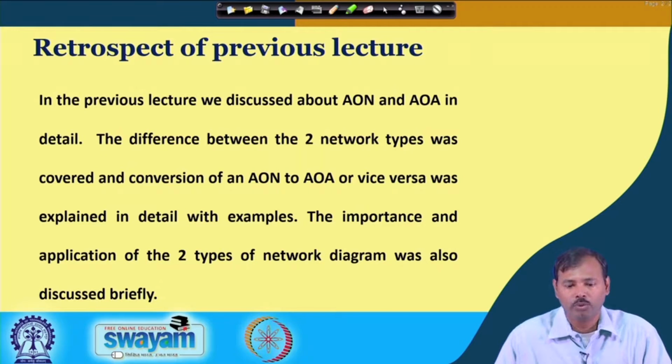But to cater to that problem, the activity on node diagram is much easier, where the jobs are identified in the nodes and thus the predecessors and successors can be easily connected with arrows from one node to another. In the activity on arrow diagram, the nodes only show the initiating and terminating points, and that is why arrows are depicting the jobs.